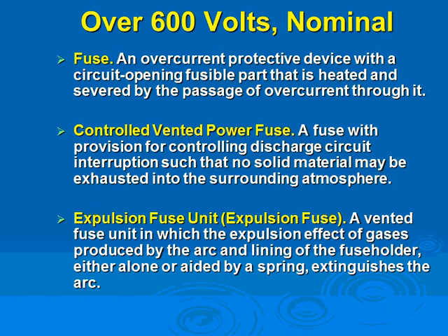Now you talk about oil circuit breakers. Utilities use them all the time. And then the next step is vacuum. So they interrupt in vacuum tubes. There is no air. They have vacuum tubes with the contacts inside them, empty of air. When they interrupt in vacuum, there's no arcing. If they interrupt in oil, the oil will extinguish the arc.